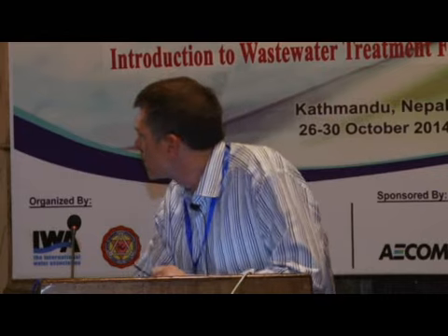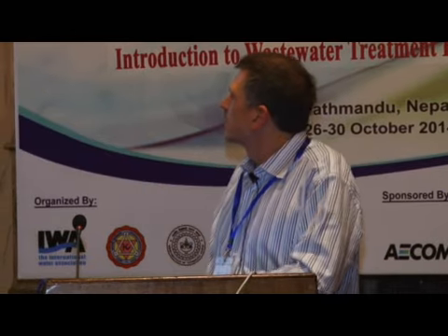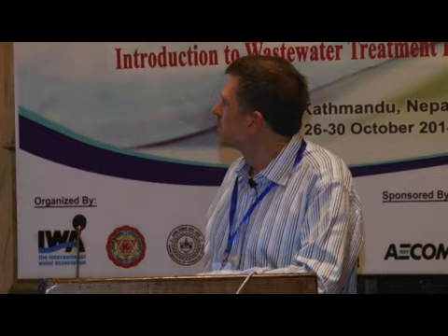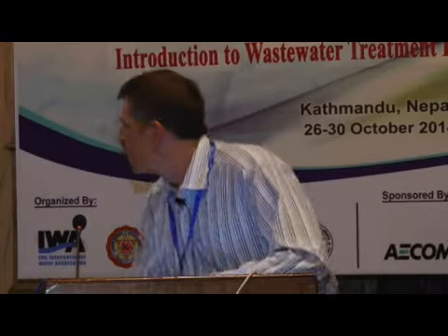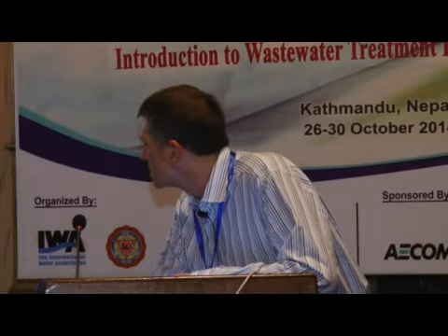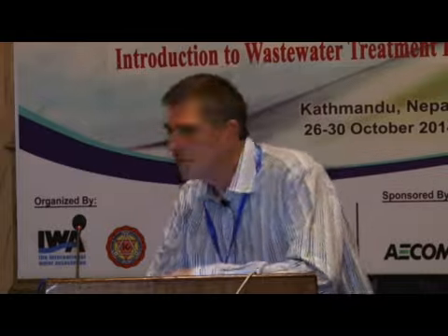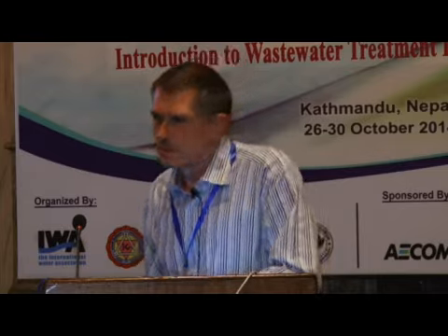And we see a lot of nitrate, 29 milligrams of nitrate. For phosphorus, there was something like 7 milligrams in the influent, if I remember correctly. And then what's coming out here is 4.1. So I guess the 3 milligrams that you mentioned, Krishna, is about right in this case. Or we made a model such that it will be right to what Krishna says.